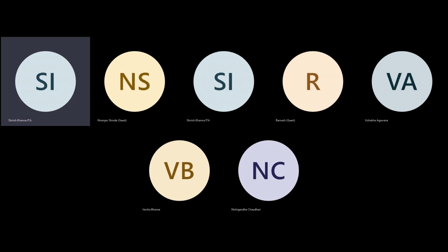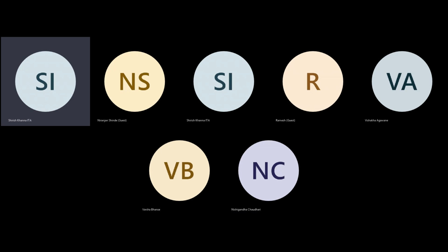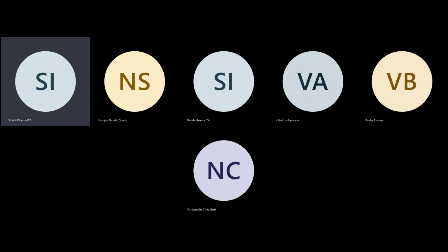Try to use it properly and create one grid system. Basically, you are going to use one CAD plan first. Try to import it into this, and where the foundations are available, place the foundation there. Tomorrow I'll show you how to change the dimensions, because everywhere is not 1800 1200 or 2400 1200. Yes, it should be changed. I can show you tomorrow.